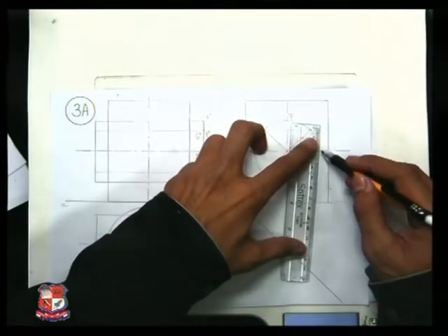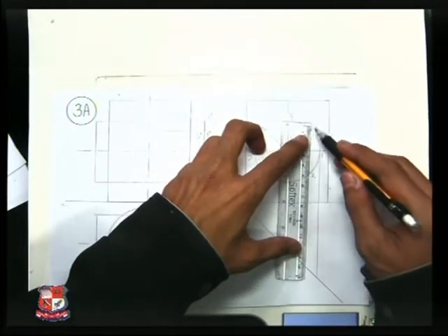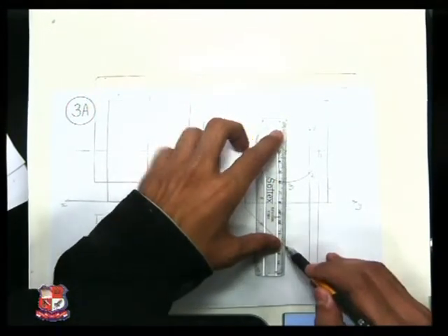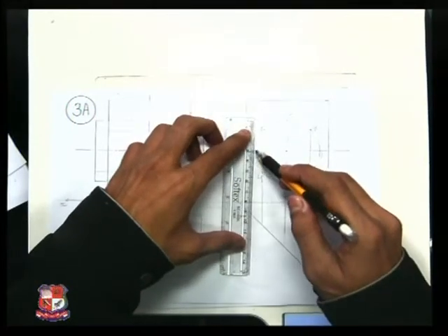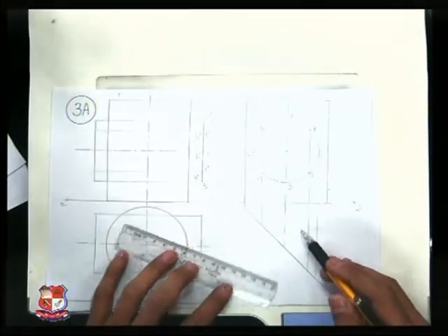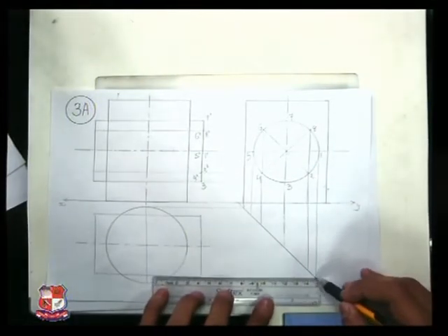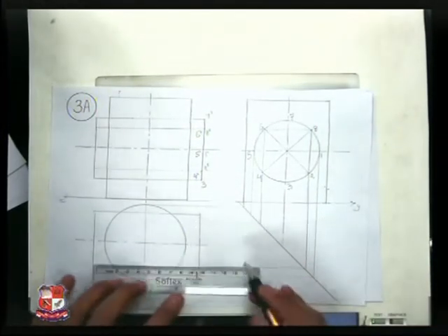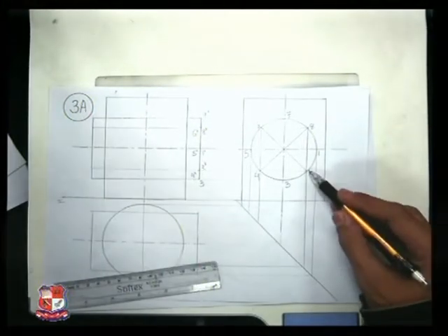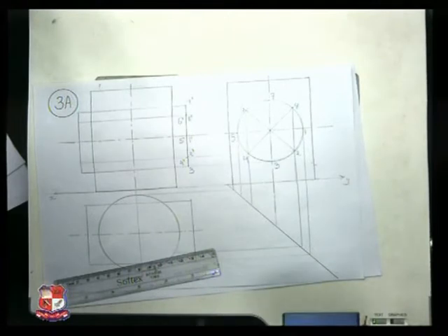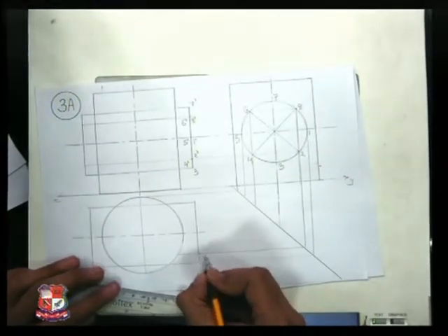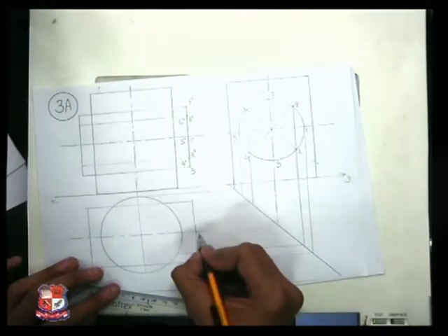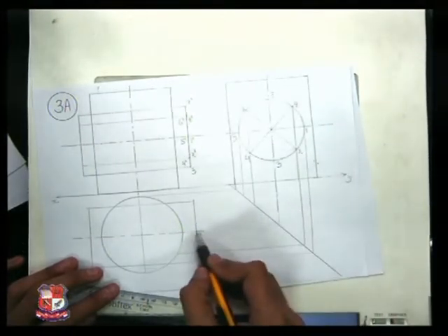Similarly, these points can be transferred to the top view by taking projections from the side view like this. Draw vertical lines from all these points and transfer to the miter line, or say mitre line, and these vertical lines will cut this miter line at some point. From that, draw a horizontal line. Here also transfer those points over here. So this is point number 1, point number 1 would be here, point number 2 is here, point number 3 is somewhere here. The intersection of this line and this line is point number 3.